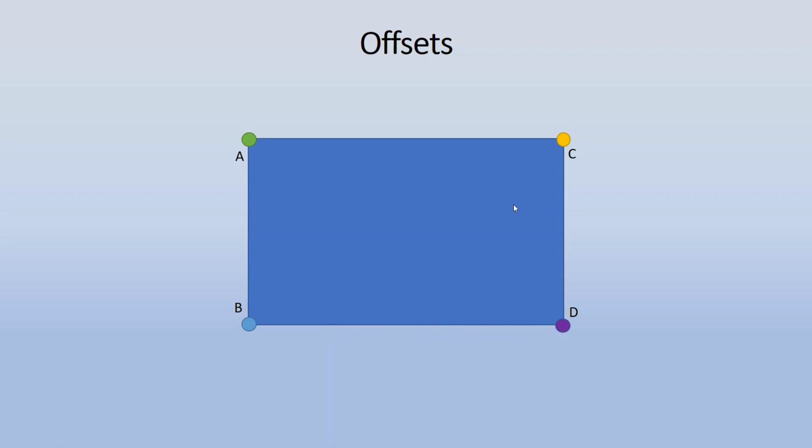So we set offsets to the actual feature, and those offsets are generally in line or square or perpendicular to lines of those features. They could be both directions, and it's not uncommon for a four-sided simple rectangular figure to require 8 offset points, offset points going each direction off of each corner.